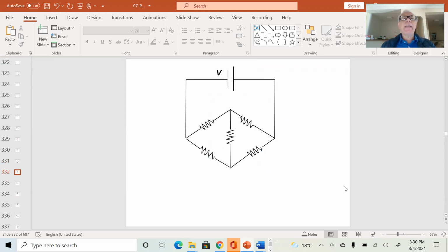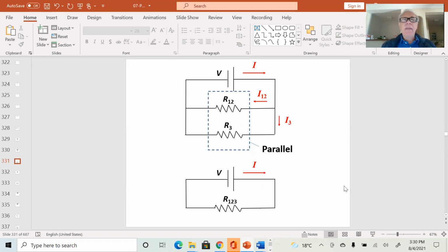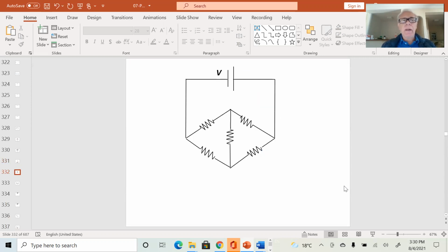Okay. And now when we get to this point, like I said, not every element can be connected in series and parallel. You can solve most of the circuit problems by recognizing that elements are either in series or in parallel. But then we have those oddballs out there which are connected neither in series nor in parallel. That's the case of the bridge circuits.